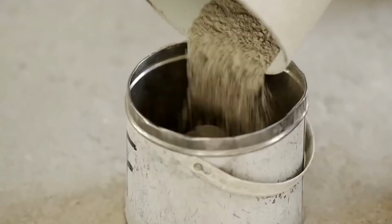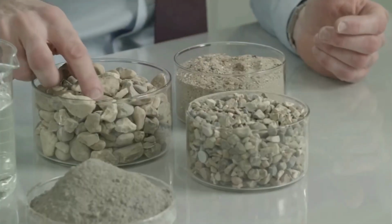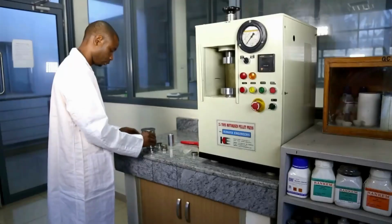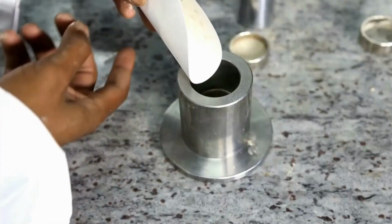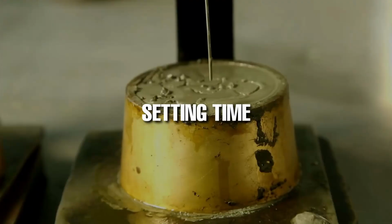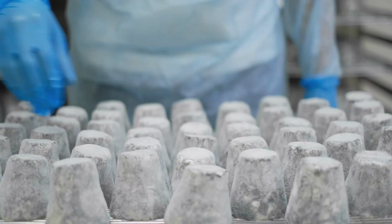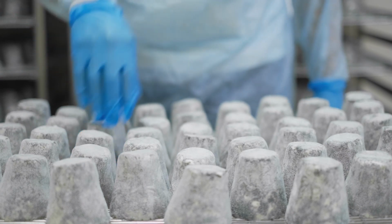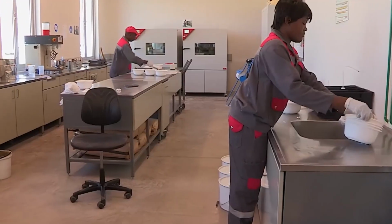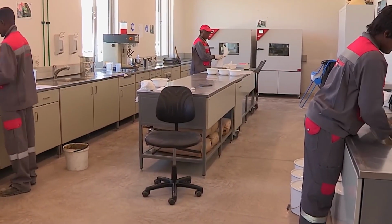After each batch of cement is manufactured, samples are collected from various stages of the production process. Once the samples are collected, skilled quality control technicians perform tests to assess various properties of the cement, including fineness, setting time, compressive strength, and chemical composition. These samples undergo a battery of tests to ensure that the cement meets the stringent quality standards set by regulatory bodies and the company's internal benchmarks.